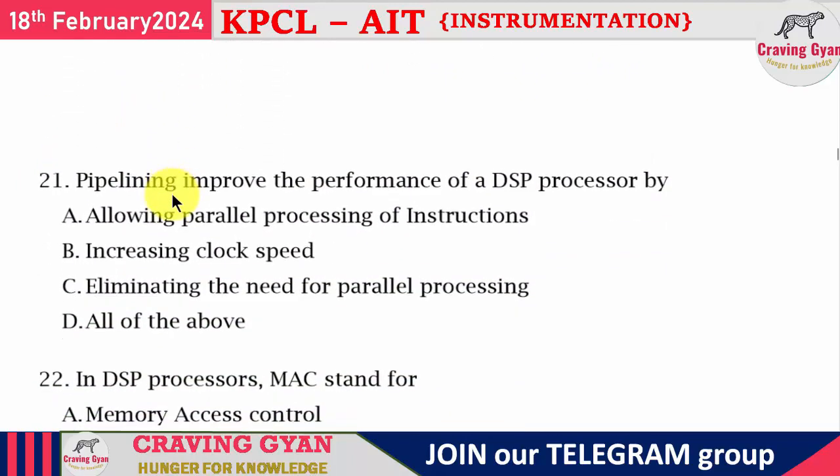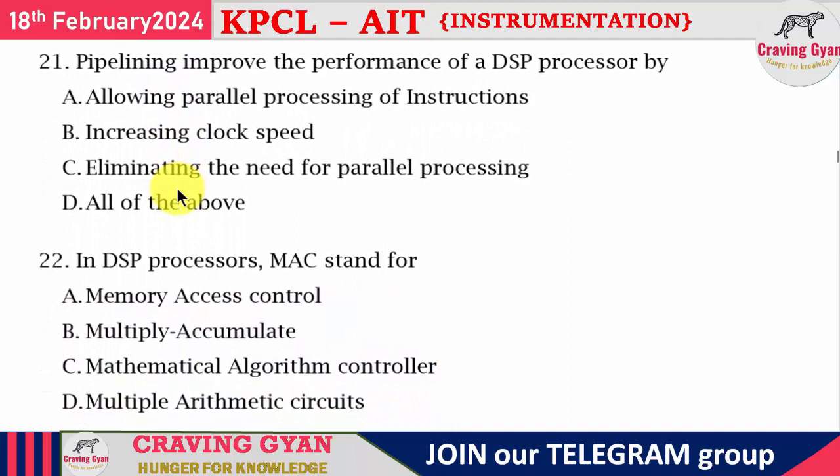And the next question is based on pipelining. This question is applicable even in microprocessor 8086 as well as in DSP processors. So here what they are asking is, pipelining is the one which improves the performance. When one instruction is being fetched, the previous instruction is being decoded, and the instruction before that can be executed. All these things are done simultaneously. So this is used for parallel processing of instructions. Option A is going to follow.